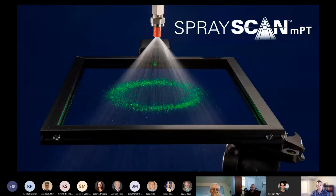But imagine having a tool such as this in the field to where we can say, hey, perhaps we're only 5% over spray capacity. This nozzle is technically good, but whenever we can conceptualize it and characterize it, then it's way out of line for very sensitive processes. Rather than sticking that nozzle back in, which might cost 50 to $100, it can throw up a trigger to say, hey, perhaps we need to reassess this. And the cost implications are simple, rather than plugging it back in and going another 5 years on that turnaround.